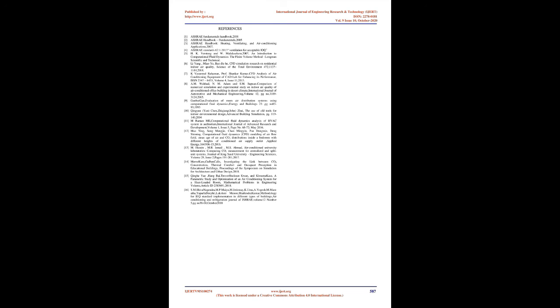Occupants have a major impact on the temperature distribution of the bottom half of the laboratory. Change in temperature for the laboratory is about 5 to 6, for experimental as well as simulated values. Also simulated values for temperature are a bit lower than experimental values. This is due to the fact that an airtight model is considered for simulation. Values for humidity ratio fell close to 40%, which can cause a certain level of discomfort for occupants at certain temperatures. CO2 concentration has crossed the limit of 1000 ppm at the very beginning itself, which is the limit set by ASHRAE.